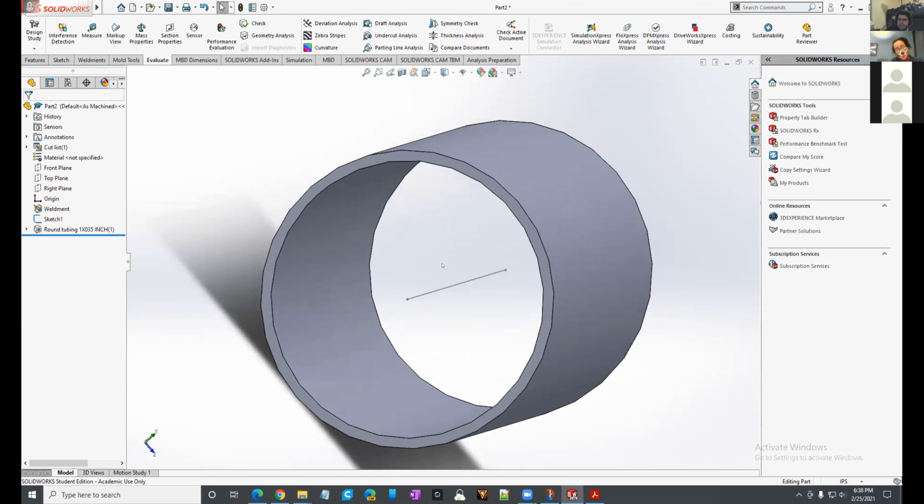It's probably easier to draw most of it 2 dimensions. Just the wide bar, the main body, and then the part that goes around the car, around the roll hoop, that can be drawn 2 dimensional, and then we can just put weldments over that and turn it into a tube. And then for the 3D sketch to make whatever part comes off of that and provides a jacking angle for the rear axle, we can go over that later.